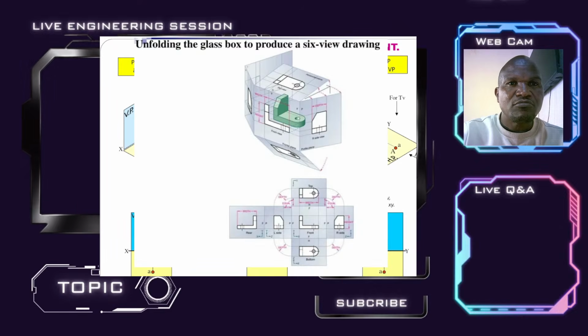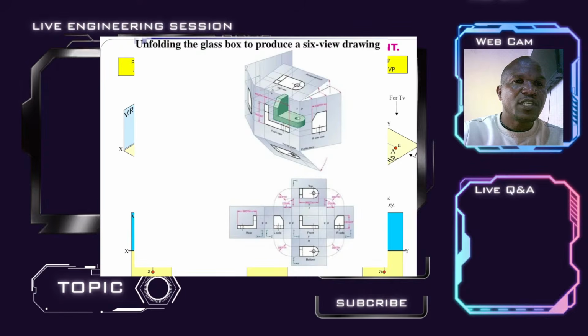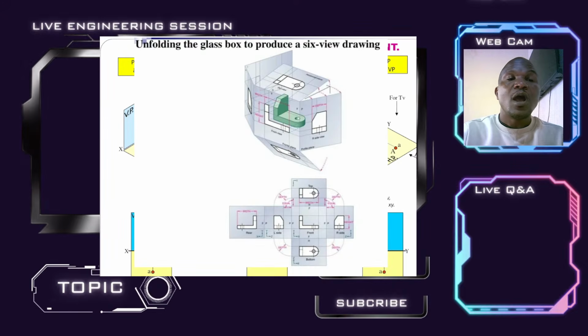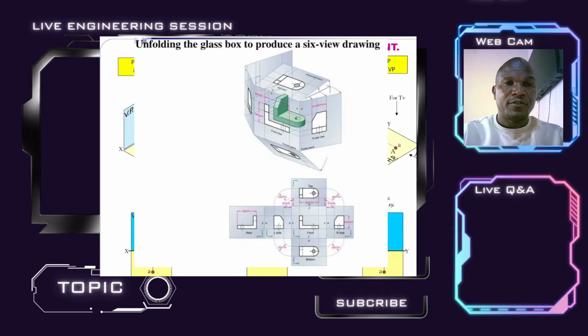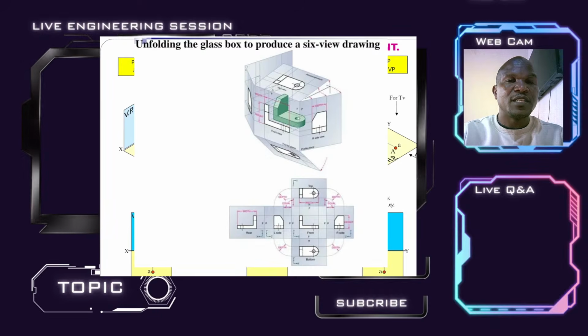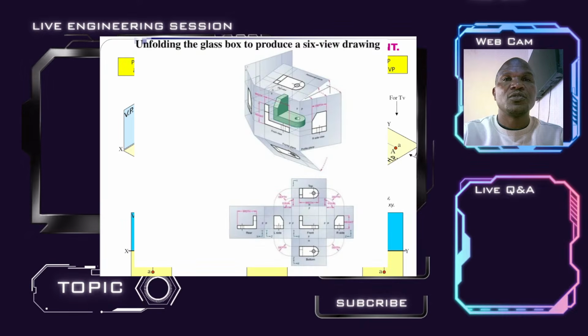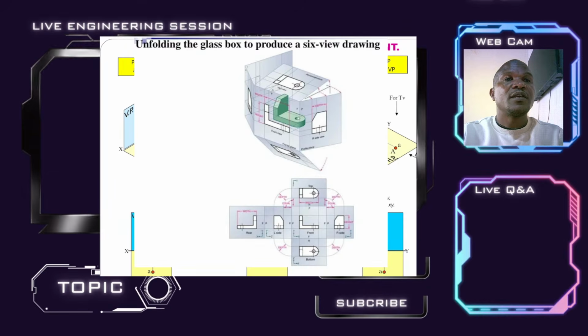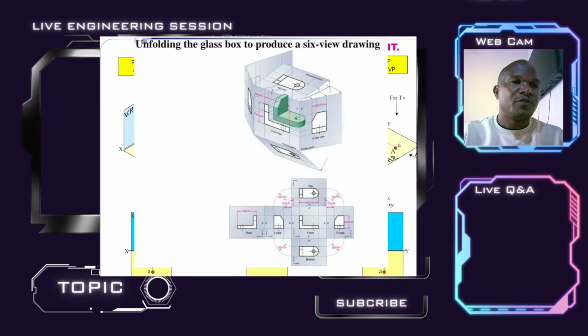Now I will go straight away into the actual orthographic views, to be able to recommend when and how you're supposed to select the front view to give you the most descriptive features, the longest line, the longest length or depth of the front view, among the other key recommendations or guidance given to you in selecting the most descriptive view as the front view.